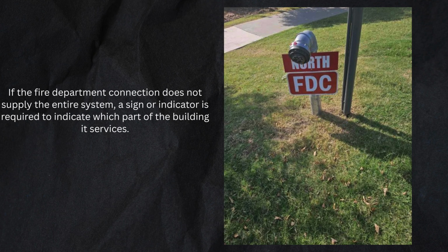If the fire department connection does not supply the entire system, a sign or indicator is required to indicate which part of the building it services.